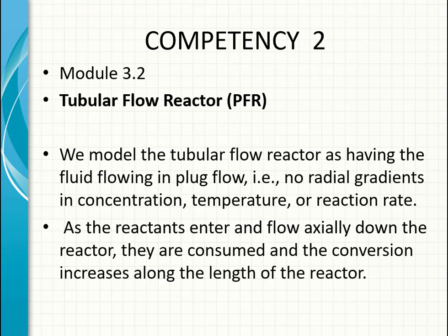Now, the tubular flow reactor, the PFR. We model the tubular flow reactor as having the fluid in plug flow. And we remember that in plug flow, there are no radial gradients in concentration, temperature, or reaction rate.